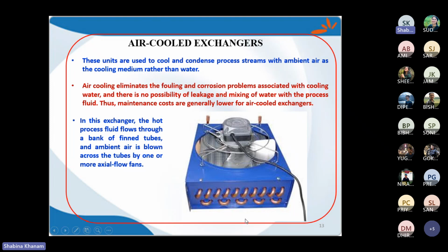Therefore it is called an induced draft fan. Once it is placed over the top, it is called forced draft because it is throwing air into the system. However, when it is induced draft, it will take the air from the system, creating negative pressure or vacuum over here, right?